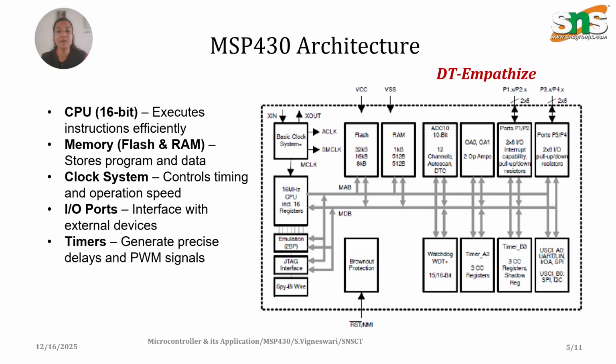And this is the MSP430 architecture. At the center is the 16-bit CPU, which executes the instructions efficiently. The memory system includes flash memory for program and RAM, random access memory, for data. The clock system controls how fast different parts of the controller run. Input output ports allow communication with the outside world, and timers generate precise delays and PWM signals. Every block is designed for energy efficiency.